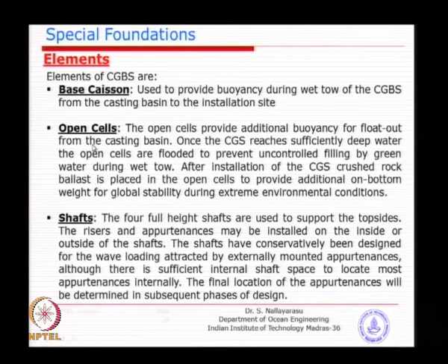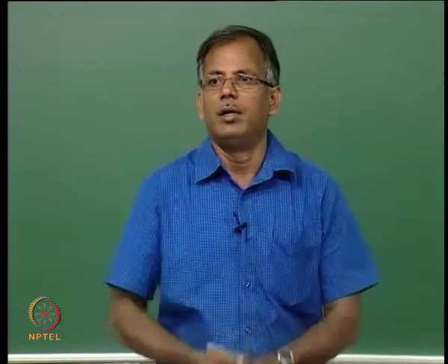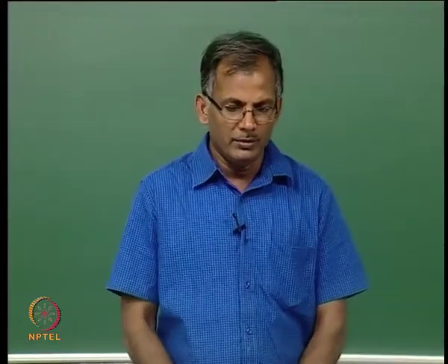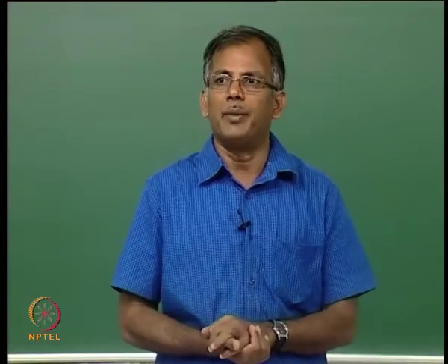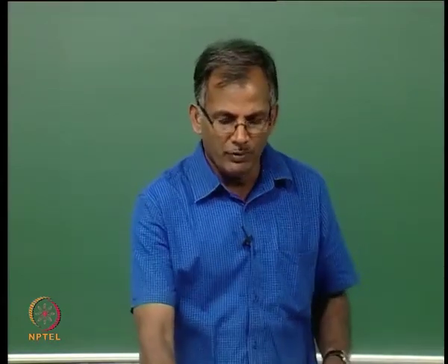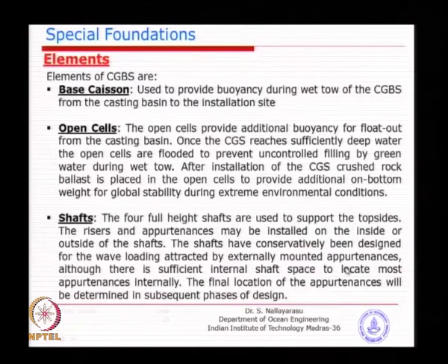The closed cells always have controlled ballasting, deballasting, which you can pump water or you can remove water from the cells, whereas the open cells only automatically flood once it gets submerged. But the advantage is you have provision to go and fill up solid ballasting.